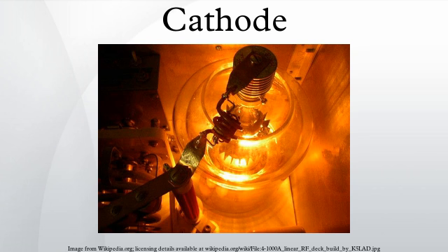In equilibrium, with no applied bias, thermally assisted diffusion of electrons and holes in opposite directions across the depletion layer ensure a zero net current with electrons flowing from cathode to anode and recombining, and holes flowing from anode to cathode across the junction or depletion layer and recombining. Like a typical diode, there is a fixed anode and cathode in a Zener diode, but it will conduct current in the reverse direction if its breakdown voltage or Zener voltage is exceeded.